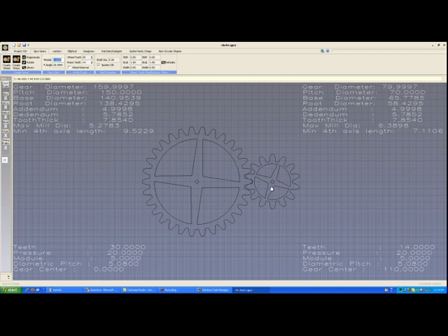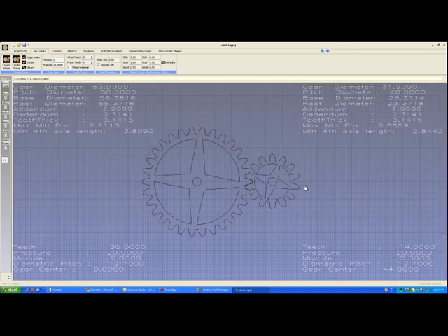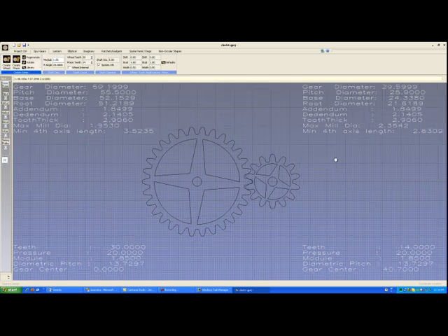All the other gears in this clock were made at module 2, I might add. So if we go to module 2, we can see we have a 44 millimeter gear distance. Well, that's just not going to fit to the center shaft. So what I do is I take my module and begin to go downwards, and at 1.85 we'll find we have a center distance of 40.7.